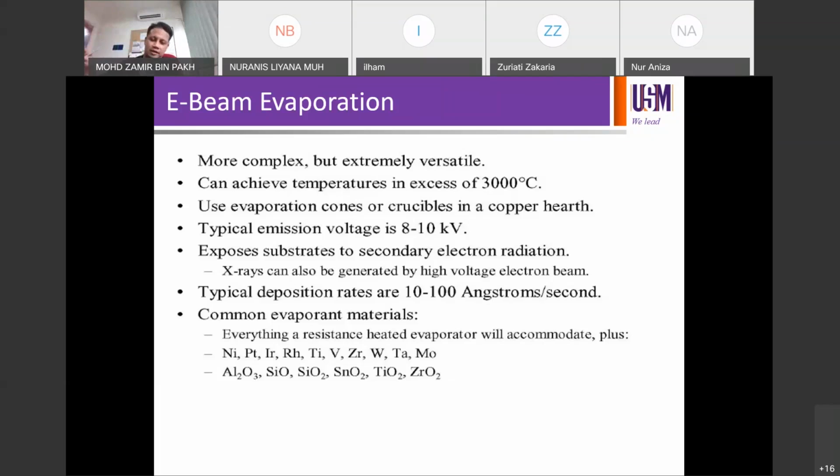So nothing actually happens. The current is too high, but it is not enough to melt your material, so it will just jump off the boat. And when you vent the chamber and open it, you look and the powder is no longer there, it's all on the floor, right? So nothing happens. That's why you need another system to do the job.